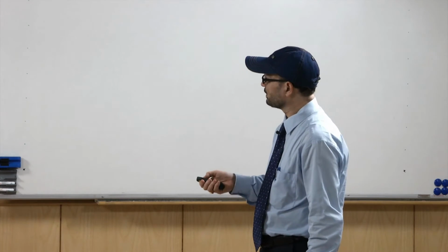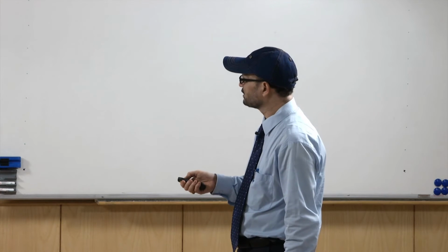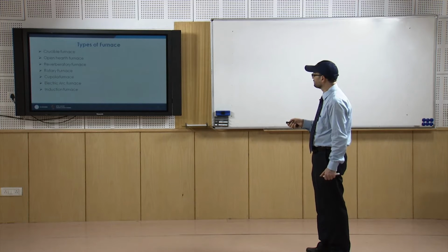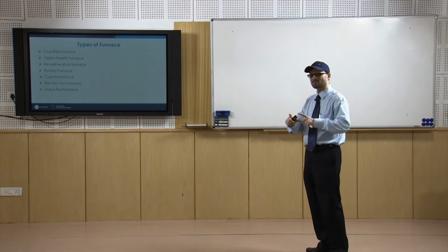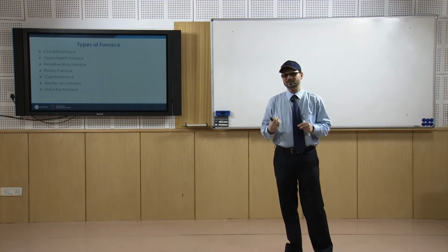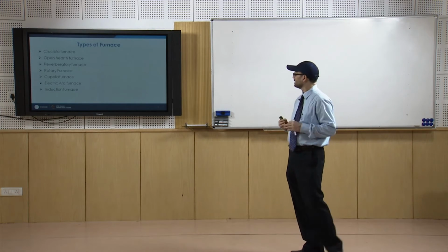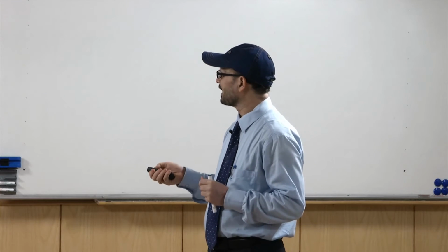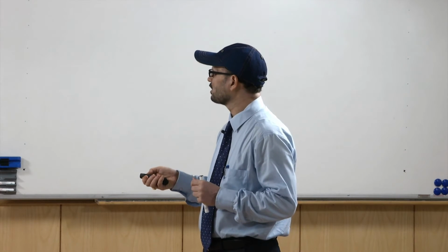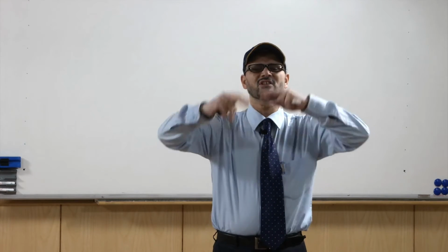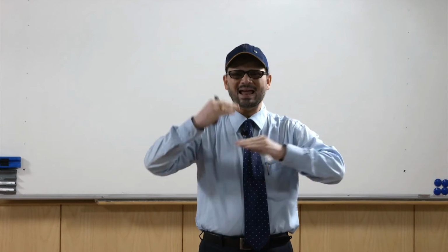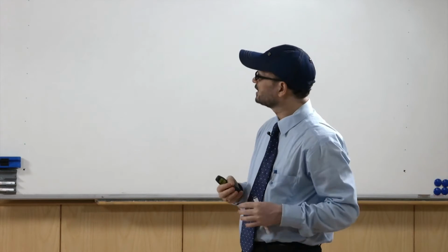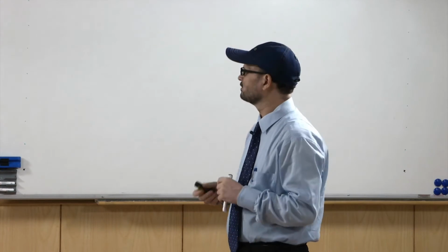Similarly, you have the open hearth furnace, where you have the principle of regenerative heating. Then you have the reverberatory furnace, a cylindrical type of furnace where the heating takes place by the flame, and because of radiation after heating the furnace lining, you have the heating mechanism. In the rotary furnace, the shell is rotating, so the linings are heated by conduction and convection, and the metal gets heated as well as by the radiation heat from the flame.